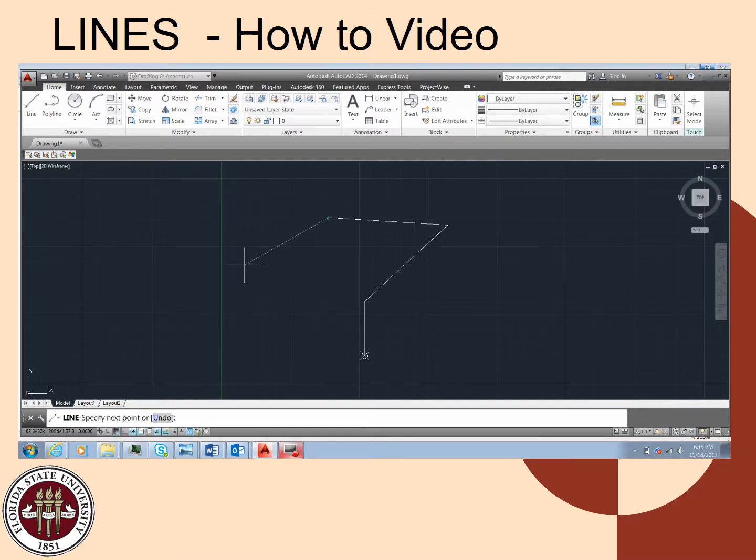I'm just going to finish this out for the sake of this exercise. Obviously, you would have different lengths and coordinates. Okay, after I've installed the complete transit, I'm going to install points on each node. Notice that it snaps to the nodes.